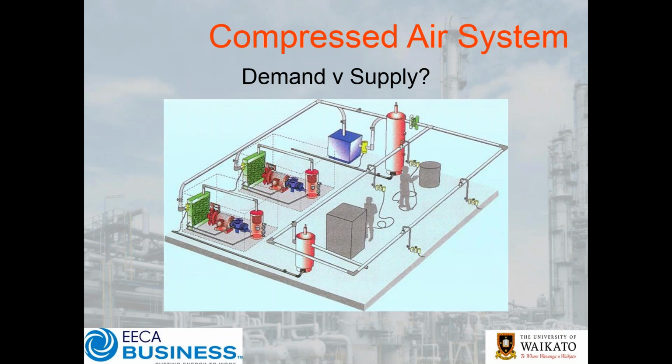So what we tend to do is split the system up into two main sides: the supply side, which is everything there in color, which is effectively our compressor. Looking here at our compressor, we have a dryer in this particular situation, a couple of filters: one here after the compressor, another one here after the dryer. We have a receiver, and generally after the primary receiver, we would consider everything downstream from that our demand side of the system.